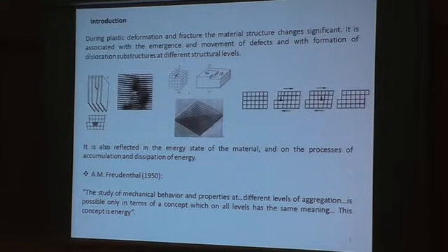So, if we start with several words about motivation, what does plastic deformation mean? When we speak about plastic deformation, we speak about defect evolution: initiation, motion, annihilation. Now we consider the solid as a hierarchical multi-level system, and each level of the system should be described. There are many ways to do it, and one of the most powerful from our point of view is to consider the energy balance in the solid.